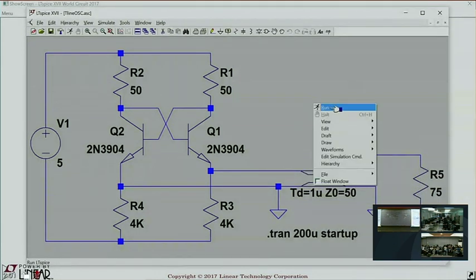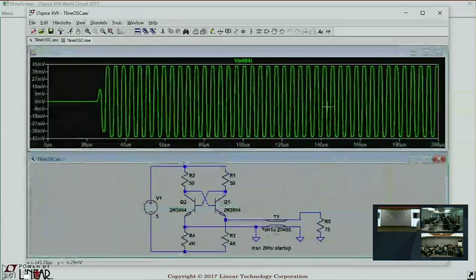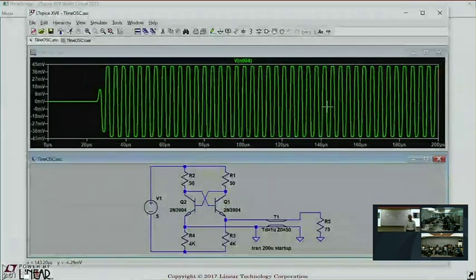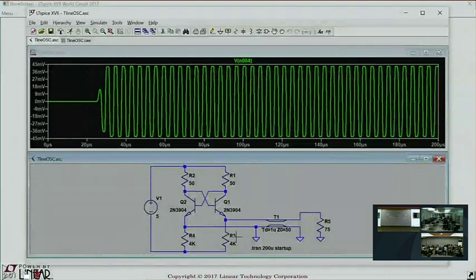But the circuit oscillates. And the reason why it does, the feedback loop has nothing to do with the oscillation. The feedback loop is developing negative resistance between these two terminals. You put it at one end of the transmission line, mismatch the other end, and you just have this reflection ringing back and forth. You should probably realize that most oscillators aren't feedback oscillators, except for a crystal or an LC circuit. You're usually charging and discharging a cap, or it's a transmission line oscillator.